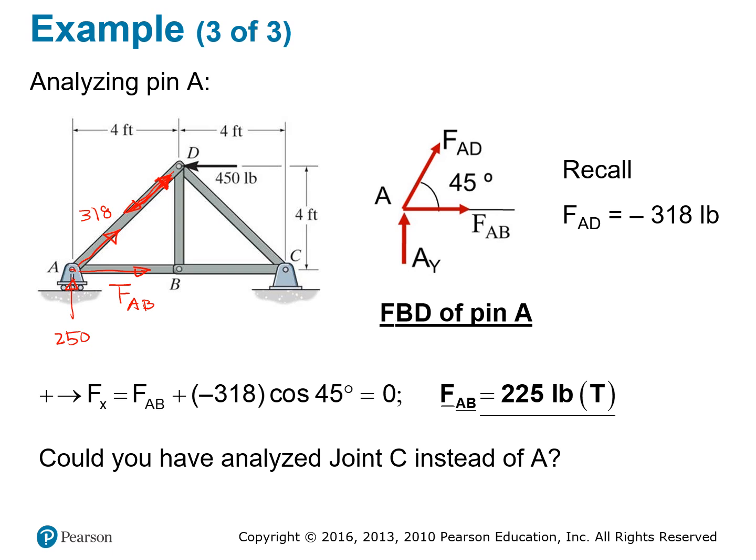With these three forces here, you can solve F_AB because this is the only unknown that you don't know about. And you can find the solution by using the summation of F_x to find what this force is. So this one has nothing to do with the x direction, so you just use 318 and decompose it, and you can find a solution. I think this one is going up.